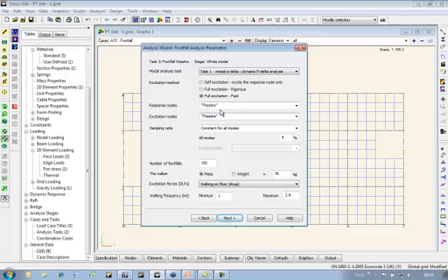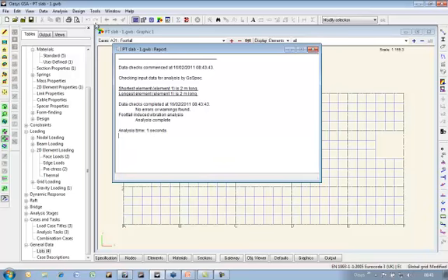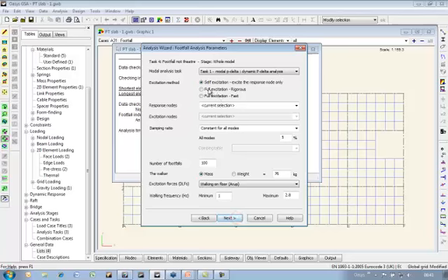Right. Operating theatre 2%. Walking speed about 1.8. Analyze that, and then do another, again a fast response is the theatre. Excitation this time all. So excitation exciting people walking outside the operating theatre, and walking speed in corridors 2.2 Hertz.